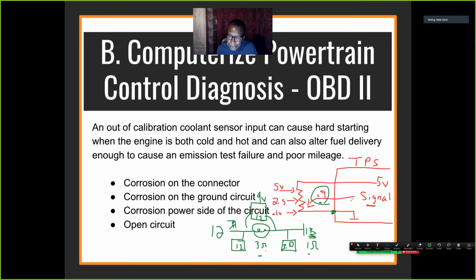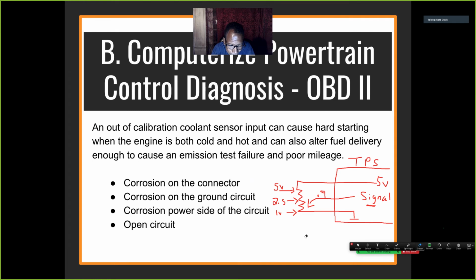Because basically this voltmeter here, this signal line here, is doing a voltage drop. So with any unwanted resistance, my voltage drop is going to be higher to push the current through that resistor, just like this picture down here. You'll see a higher voltage drop on the signal wire because that higher voltage is needed to push the current through the resistors and the unwanted resistance.